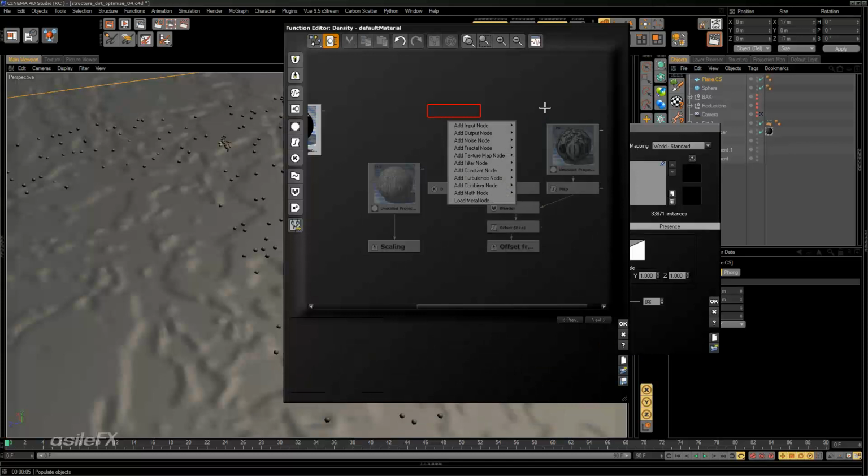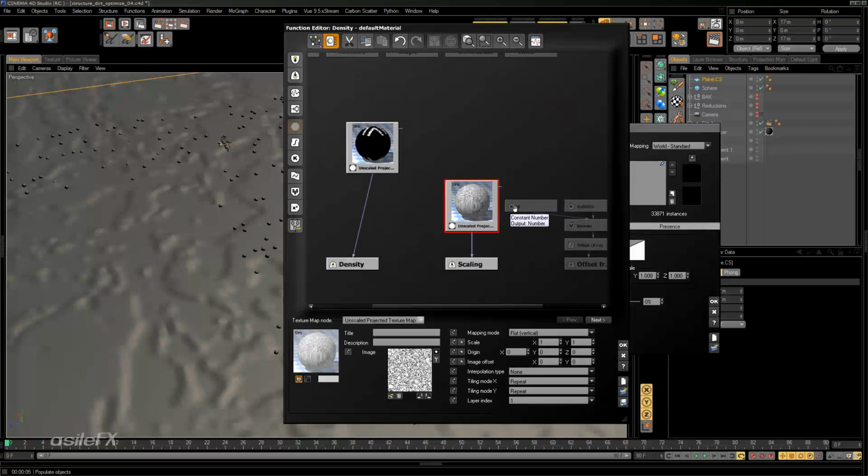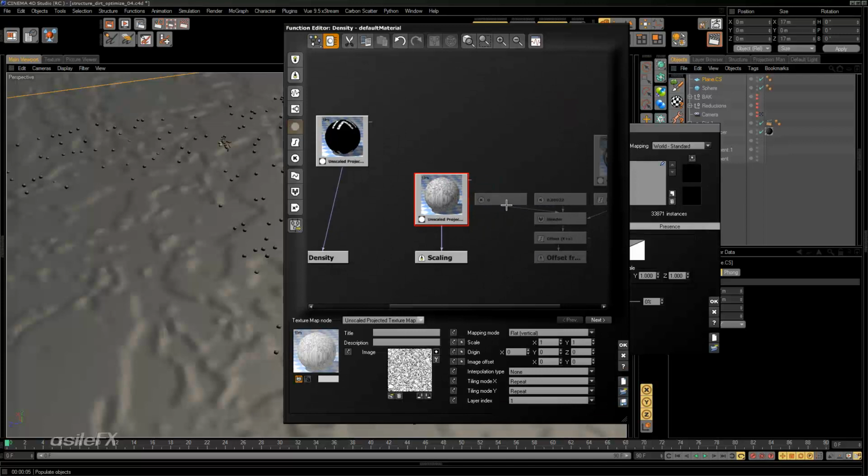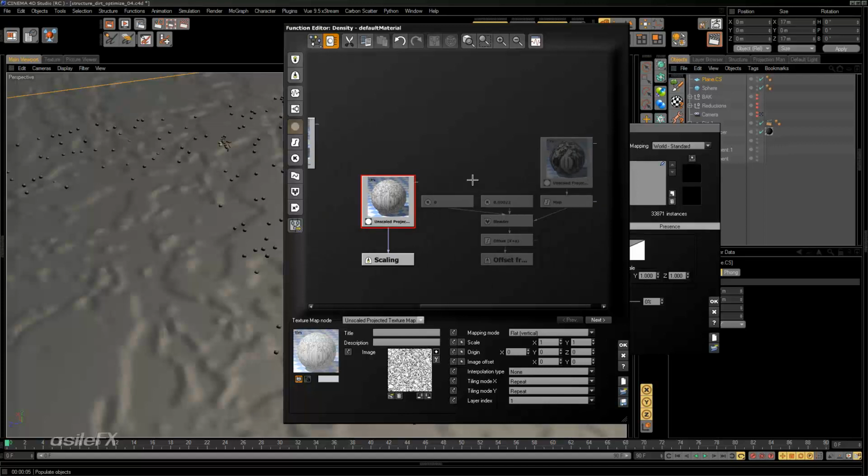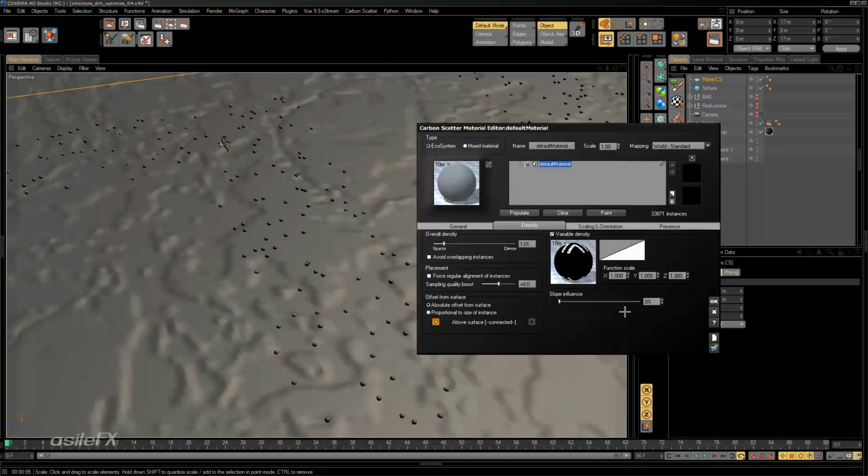version 9, and in version 9 that default gamma is 1.8, so it looks like that's kind of being carried over into this, so that can modify your images, changing that gamma. So I'm just going to override them to 1. The gamma source, the image itself is 1.8, but we do want a linear control in this case, so it's a little easier to work with. So the scaling, I'm going to set it up so the black is the slope, and that way we're going to have smaller objects on steeper slopes.